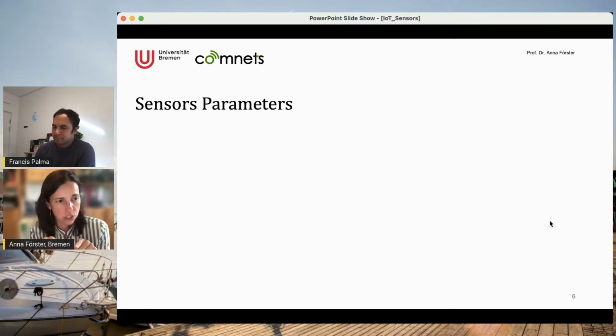Pins means a connection to the outside world where you can connect, for example, to a particular sensor or a particular actuator. Some of them are connected to your battery. Some others are connected, for example, to a real-time clock. All components which you would like to connect to your microcontroller are connected via pins. Those are these small legs coming out of the microcontroller, right?